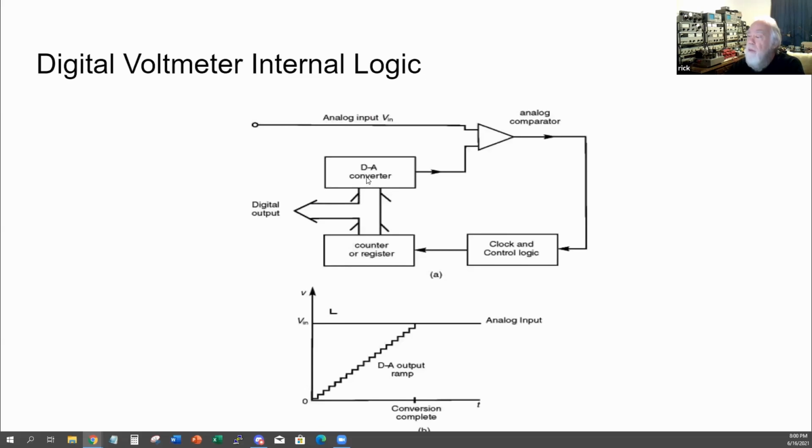making a digital voltmeter, the earlier ones before we used the digital to analog converter, we just used what's called a ramp signal by taking a capacitor charged by a resistor over a short period of time, and we took the output of that capacitor, which starts from 0 and rises to maybe 5 volts. We bring that into the comparator and compare it to our unknown voltage, and when the two become equal, now we know we have a sample of the voltage that we want to measure.